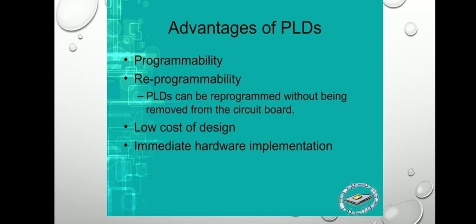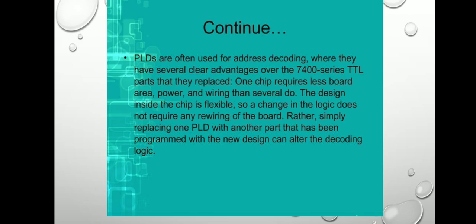Here there is also reprogrammability. A PLD can be reprogrammed without being removed from the circuit board, with low cost of design and immediate hardware implementation. PLDs have three fundamental types of standard PLDs. A fourth type of PLD is the complex programmable logic device, which has thousands of gates.